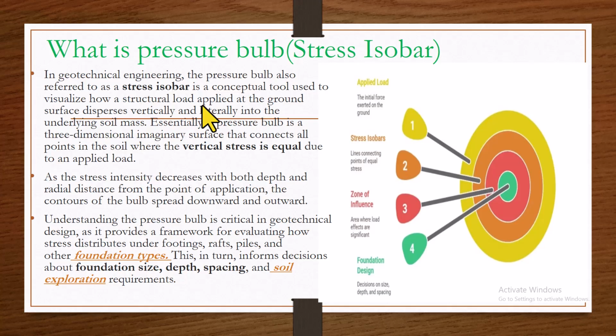So what it is trying to say is that when you apply a load, or when your footing sits on the soil, we want to know at what depth of the soil will feel the load I applied. If you place your footing at 1 meter depth, do not assume that the effect of the load will be felt only by the soil immediately under the footing.